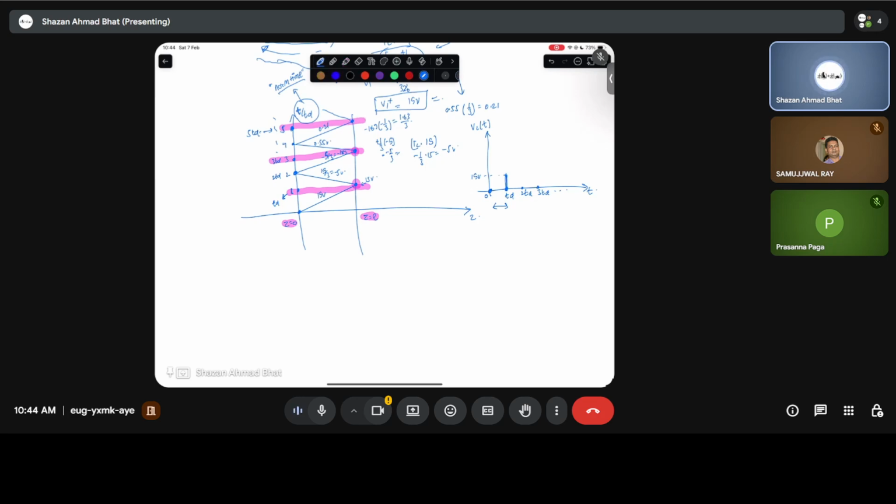So these 3 time instants are basically being plotted on this VL versus time curve. First you get to 10 volts, then it will stay at 10 volts. Then after time 3 TD, it's going to receive another minus 1.67, so it'll drop slightly.